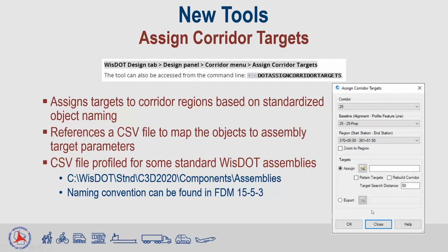But this gives you a good starting point to populate that CSV file. You start with your region, export it, and then you can set your targets up accordingly. And then above here, again, assign, here's where you select the CSV file. You have an option to retain any targets that are already set.